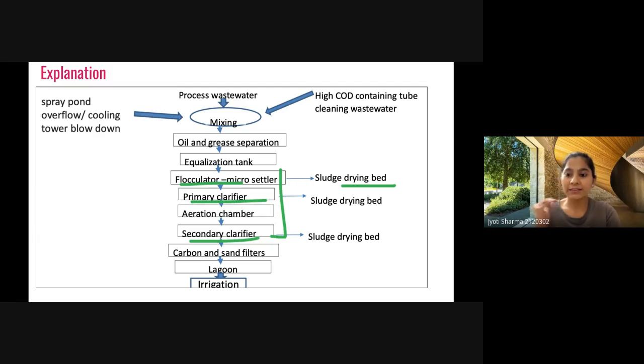We discussed a lot of techniques, and one of them is drying beds. On those beds we can spread the sludge, and this is how it can be dewatered and formed into solid. We already learned that sludge is a slurry with water and some suspended particles. After the drying bed, we will have the solid form of this sludge, which is easier for management.